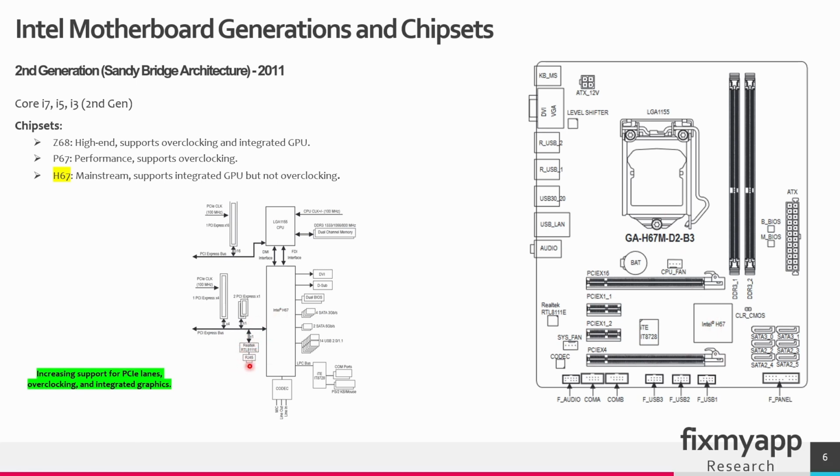Also the audio and the LAN connectivity. So these two will go, according to this image, to the chipset. Also the SATA data lines will go to the chipset. The PCIe slots with 1 data lane will go to the chipset. The PCIe Express with 4 data lanes will also go to the chipset. The BIOS clock signal and data will go to the chipset, according to this image. But the DDR3 memory, according to this image, will communicate directly to the CPU. And also this slot with 16 lanes will communicate with the CPU.